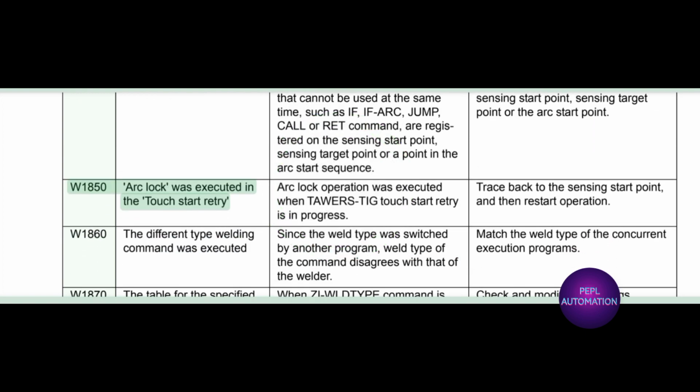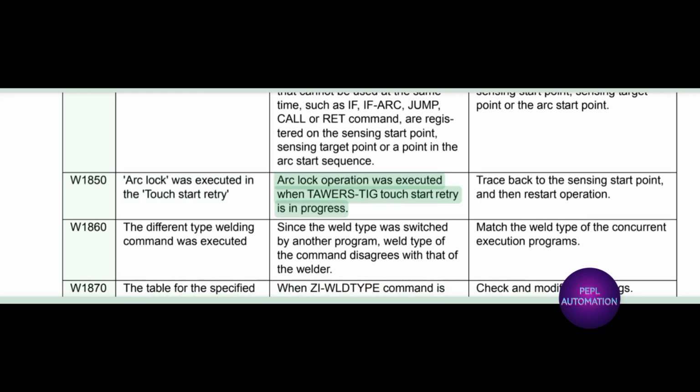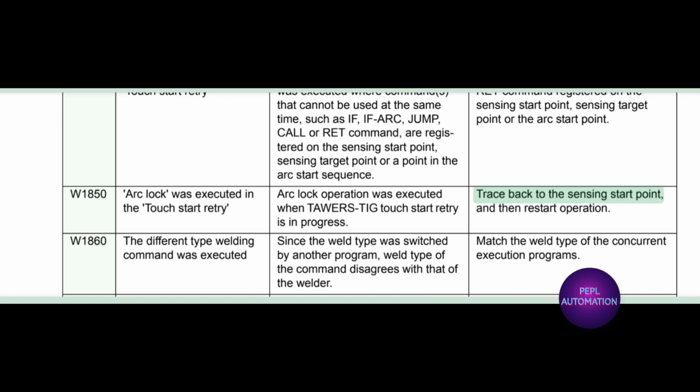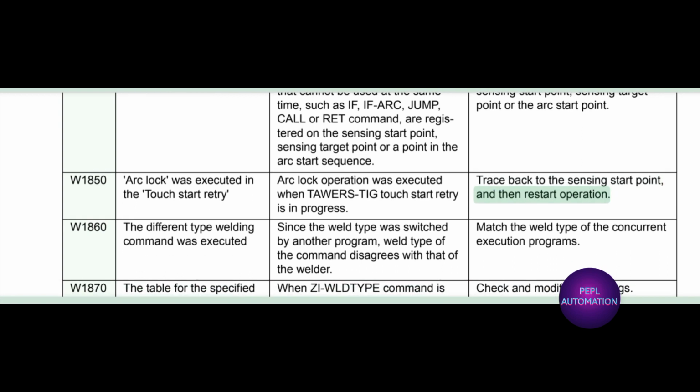W1850 arc lock was executed in the touch start retry. Arc lock operation was executed when TAWERS TIG touch start retry is in progress. Trace back to the sensing start point, and then restart operation.